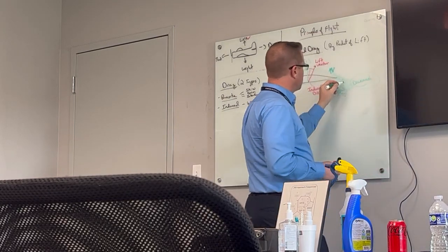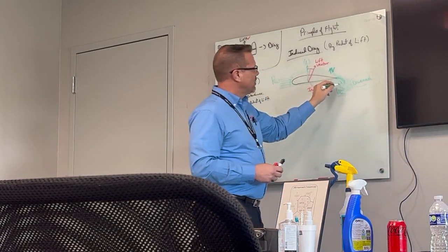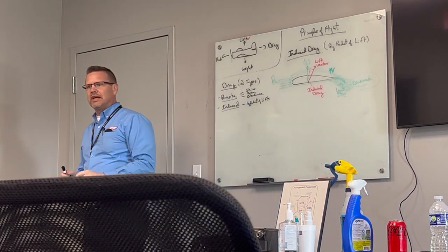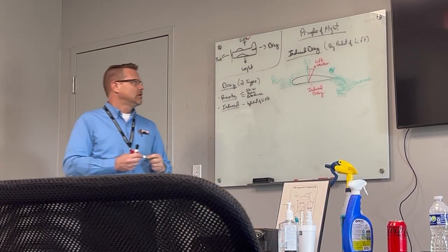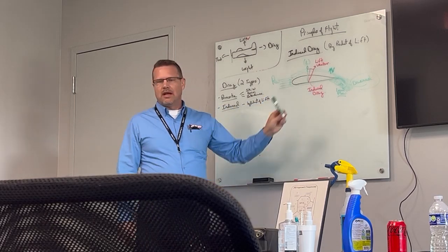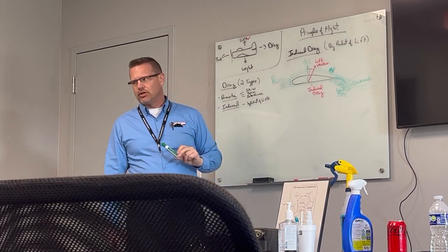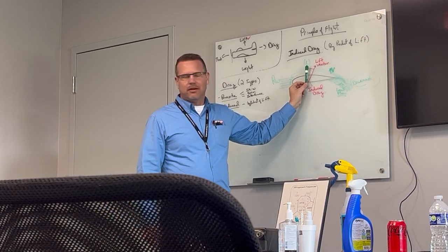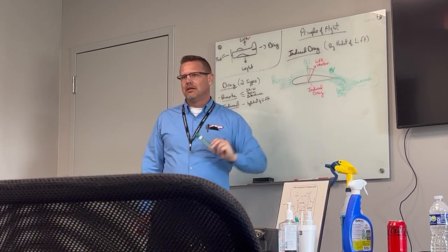And it's this disturbance of air that causes this burbling and drag off the trailing edge of the wing. In fact, so much that our lift vector, which is typically perpendicular, ends up getting pulled. This is exaggerated for illustration purposes, probably should be right next to it, but it is slightly pulled back.